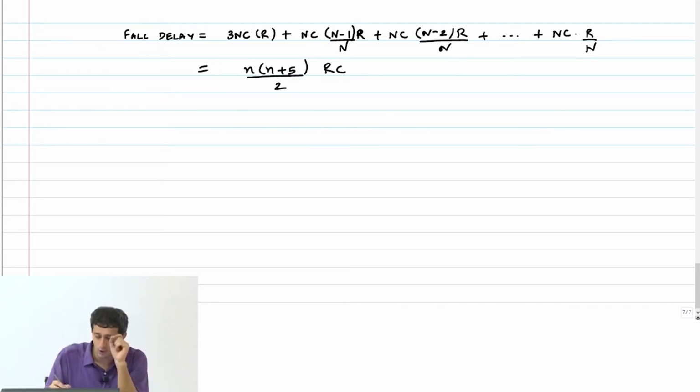The key point to note is that this delay, by the way, is called the parasitic delay of the gate, because this delay is coming in because of its own capacitances. It's not that we have added any load capacitance to this gate. Just because of its own diffusion capacitances. We have not considered even one gate capacitance here.